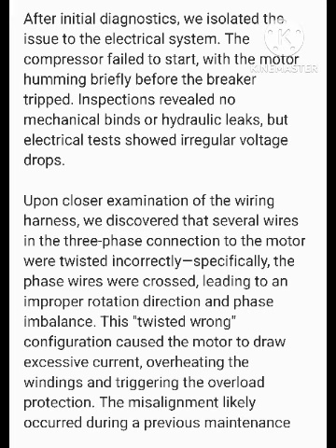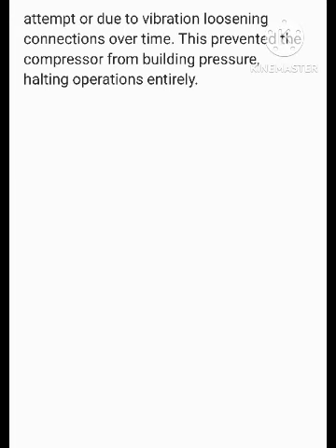Upon closer examination of the wiring harness, we discovered that several wires in the three-phase connection to the motor were twisted incorrectly. Specifically, the phase wires were crossed, leading to an improper rotation direction and phase imbalance. This twisted wrong configuration caused the motor to draw excessive current, overheating the windings and triggering the overload protection. The misalignment likely occurred during a previous maintenance attempt or due to vibration loosening connections over time. This prevented the compressor from building pressure, halting operations entirely.